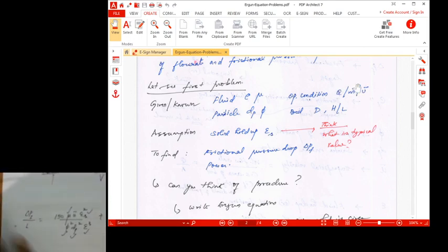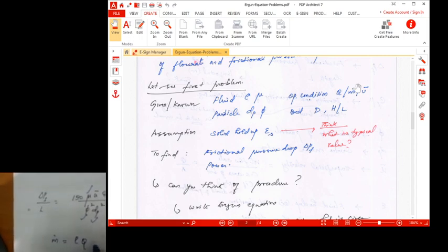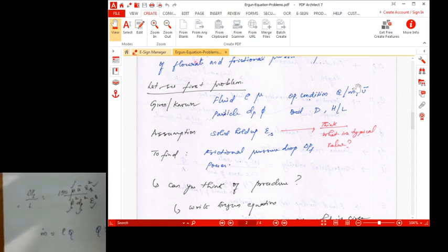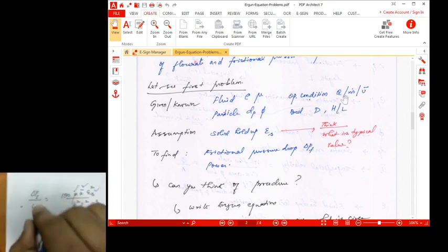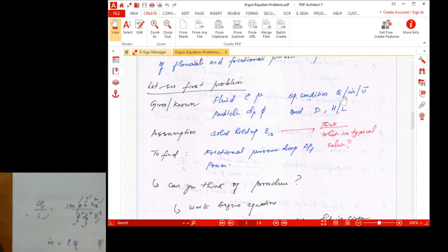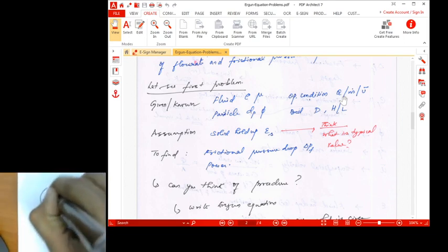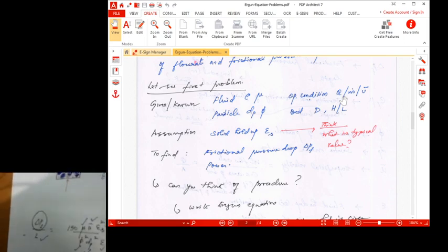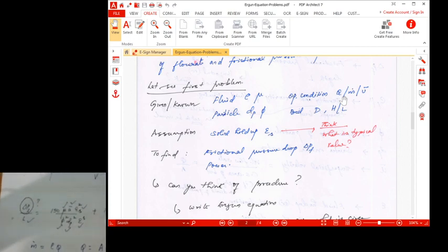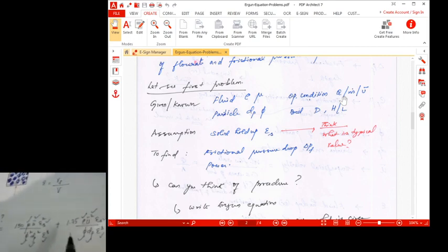So we can write the mass flow rate as the density of the fluid times the volumetric flow rate, and the volumetric flow rate can be written as the cross sectional area of the bed times the superficial velocity. So these two terms are also known, and you also know the bed dimension, so the length is also known. That means the only unknown in this case is the frictional pressure drop. So this is fairly straightforward. Everything on the right hand side is known.